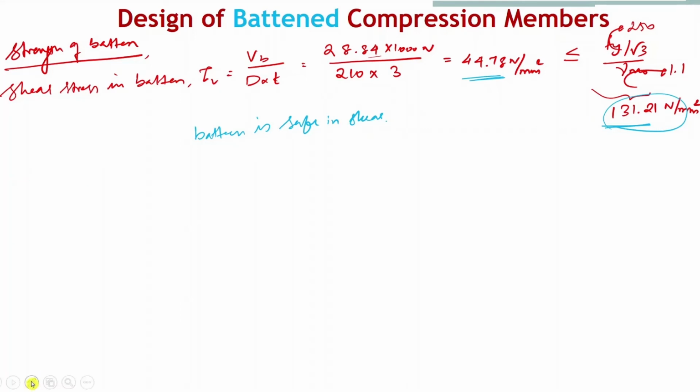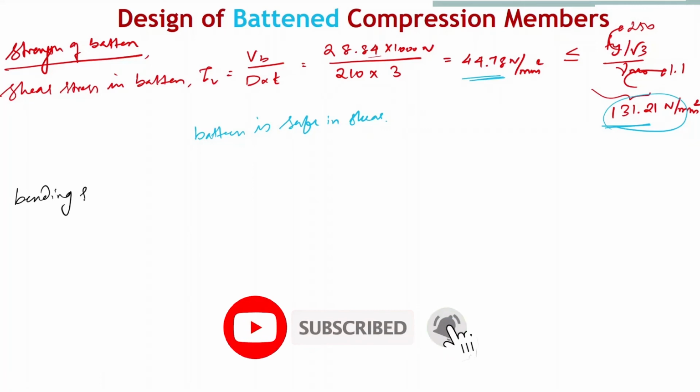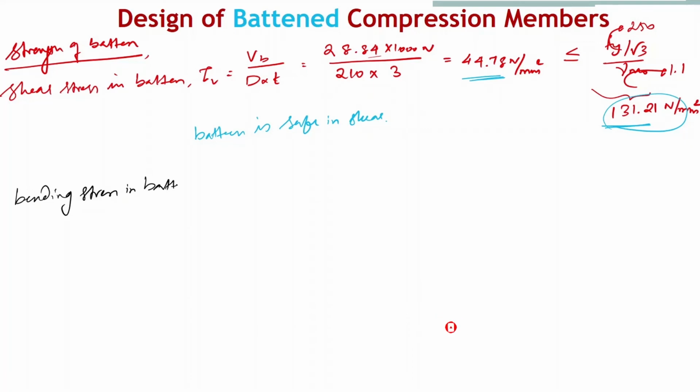So next I need to check the bending stress in batten. So bending stress Fd equal to M by I into y.